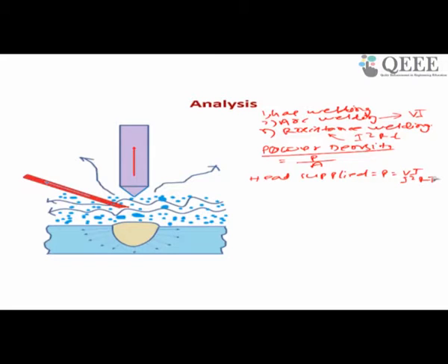Now, through the motor or through your setup, you are supplying this much power, but there are so many losses. So the power available at the tip equals the supplied power minus the losses. There are different types of losses, such as transfer losses. The power supplied comes to the tip of the electrode, and it has to be transferred from the tip of the electrode to the workpiece. In between there will be many losses. Those losses are accounted for by the transfer efficiency.